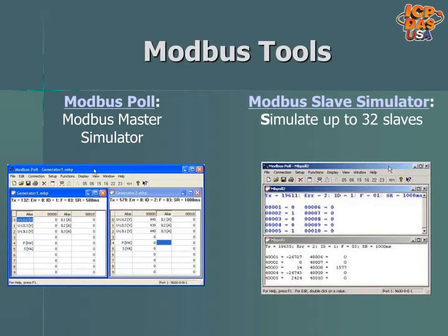It allows you to do things like read the coil status, input status, holding registers, input registers, write to registers, and things like that. Modbus uses registers to hold the data, and you can access the data and turn things on or off, but basically the status of the I/O and the measurement data, it's all stored in memory registers.